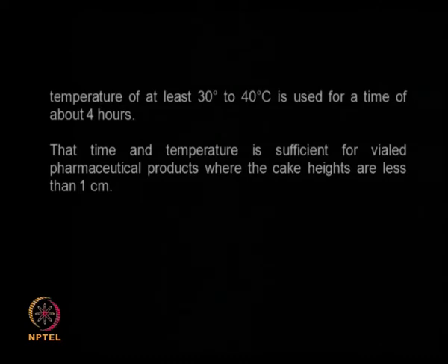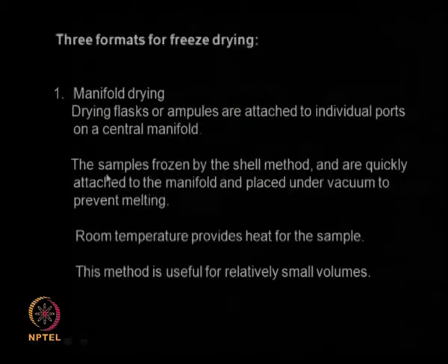You have to go up in temperature to about 30 to 40 degrees centigrade, and it may take about 4 to 5 hours. And if you have a pharmaceutical product, then you may slowly form an ice cake. Generally the cake thickness may be of the order of 1 centimeter.